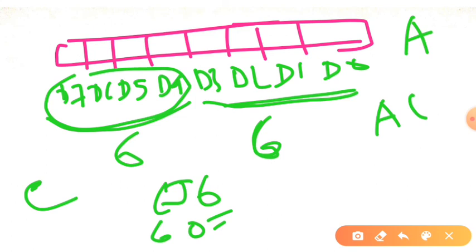So let us understand this procedure with an example. Let us assume that the ADD B instruction is used, suppose, to add two BCD data, binary coded decimal values, stored in register A and register B. Okay, and then after that addition, depending on the addition result, I will show you what we mean by simply binary data, and what is the necessity to use this DAA instruction in order to convert the result back to the binary coded decimal value.